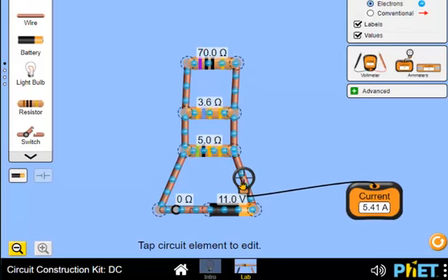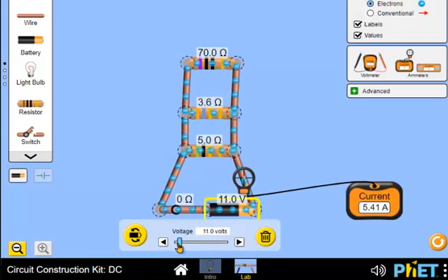Okay, so what I'm going to try here is I'm going to aim for getting 1 amp, and then I can use Ohm's law again to determine the equivalent resistance. So I'm going to drive the battery voltage down till I get to about 1 amp. Okay, close, getting close. Whoa, okay, there we go. Ooh, I'm really close. Okay, so I have 2 volts divided by basically 1 amp, which is 2 ohms, but because I shifted the decimal point here, it's actually 20 ohms, which of course was the answer we had on the calculator, 20.3 ohms. So it still checks out.